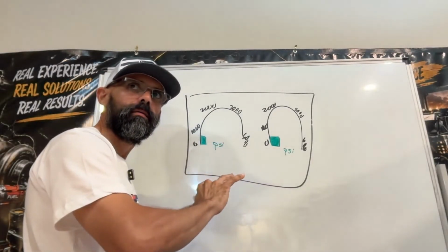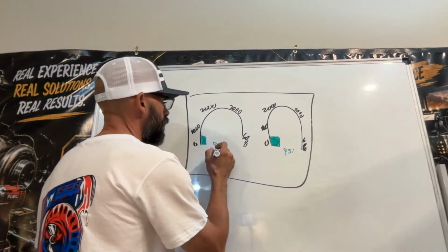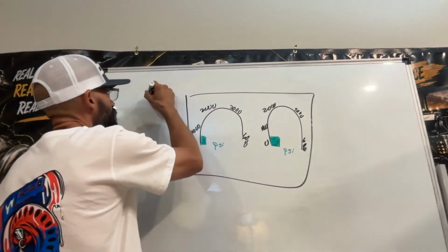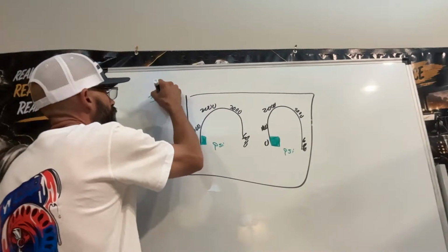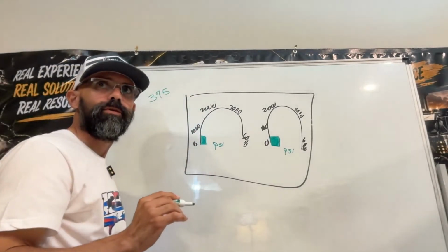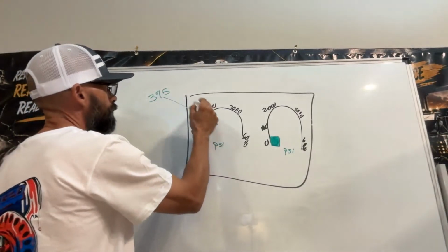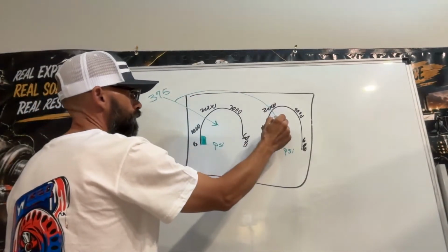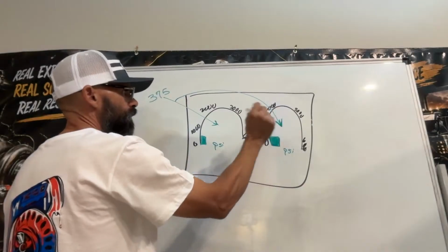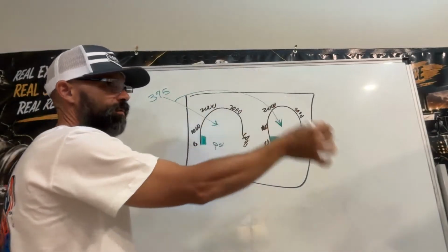At idle, you're gonna see pressure right away. So if the system calls for 375, as for charge pressure, it's for both right here and also right here, because you only have one pump supplying oil for charge pressure on the tandem pump.